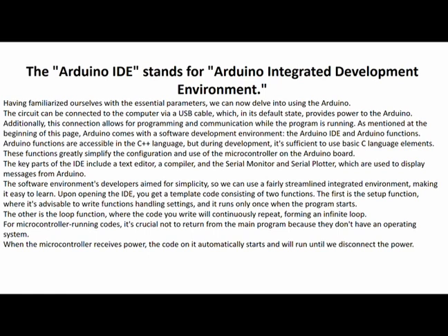As mentioned at the beginning of the page, Arduino comes with a software development environment, the Arduino IDE, and Arduino functions. Arduino functions are accessible in the C++ language, but during development, using basic C language elements is sufficient. These functions greatly facilitate the configuration and use of the microcontroller on the Arduino board. The essential parts of the IDE include the text editor, the compiler, and the serial monitor and serial plotter used to display messages from Arduino.